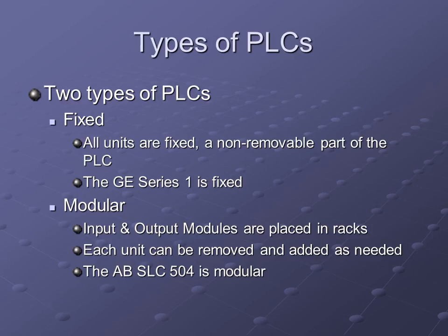But basically, this is a fixed PLC, but in this case, it's expandable. It has a little port right here that I can connect into to add additional ports. But with a fixed PLC, it would look like this without this expandable port. Basically, the number of inputs and outputs that you have on a fixed PLC is the number that you have.